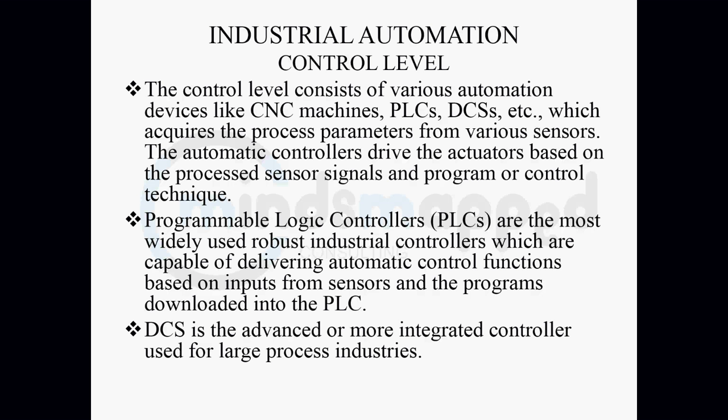But how would the PLC find out that the motor has started? How will the PLC know? Maybe it has sent out the output command, but maybe the motor is decoupled in the field. Maybe the motor is burnt out. Maybe there is a power issue with the motor. So how can the PLC be sure that the output command it has sent out to the motor was acknowledged and executed by it? By the feedback.